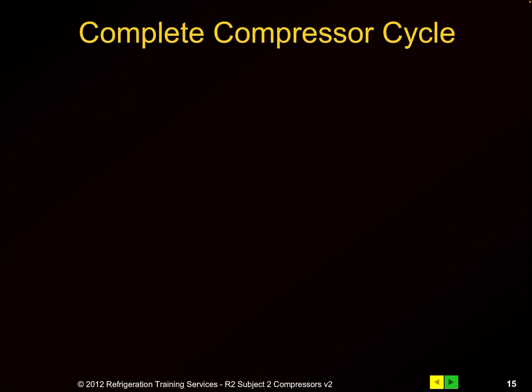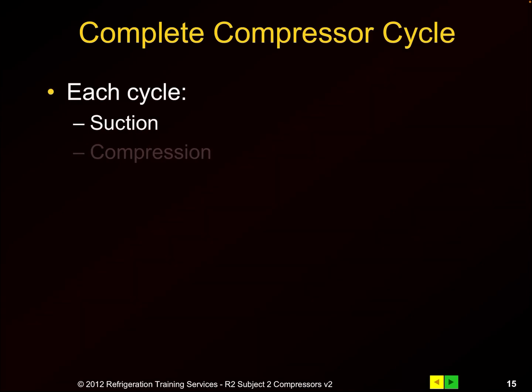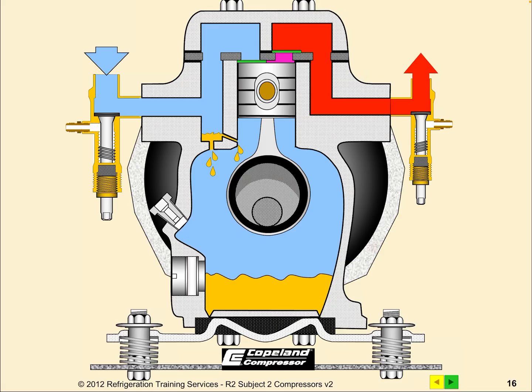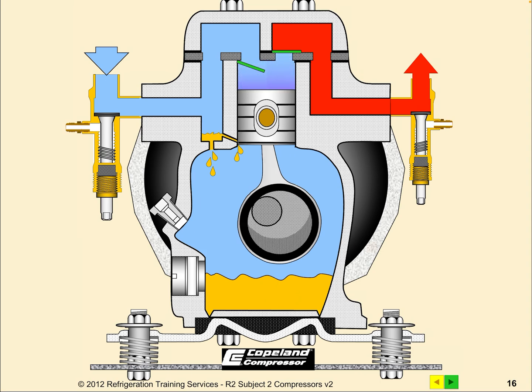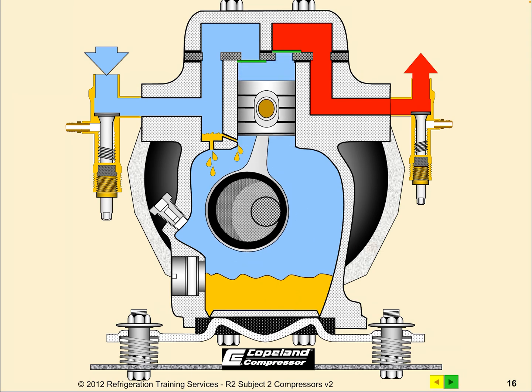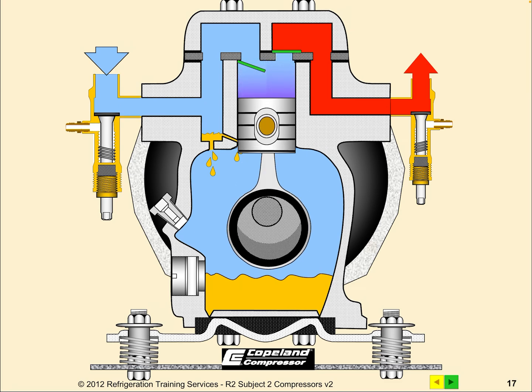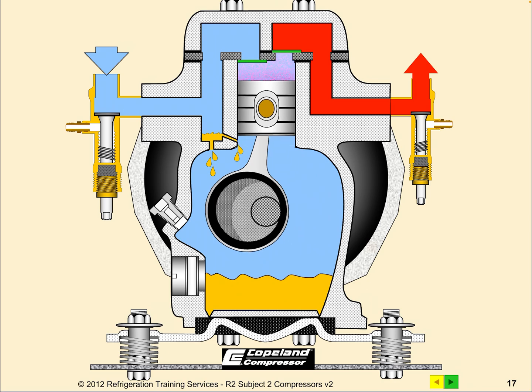And of course, once the compression stroke goes, then obviously that means the valve should have been closed. We compress it, we discharge it, and we keep going over and over again. So in this example, you can see the process happening, so that we are compressing, we're opening the discharge valve, we re-expand, we allow new gas to come in.